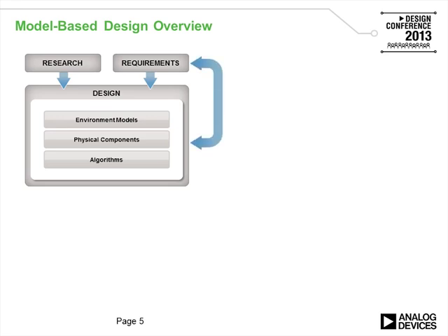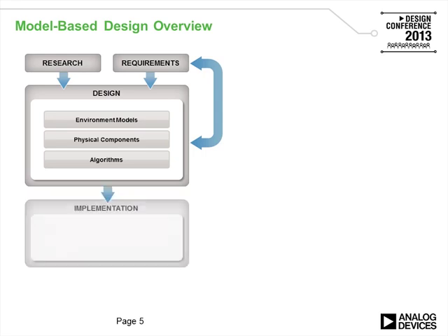Verify the system model at this level to confirm that it meets requirements. Tests you develop to verify the model against specifications now are the same tests you will use later in the design process to verify your implementation. If requirements change, you just need to verify that the system model meets the updated requirements at this level, and the changes will flow down through the process.